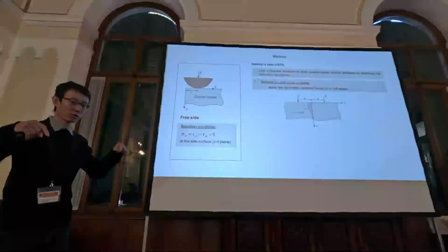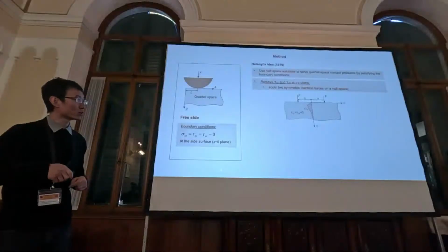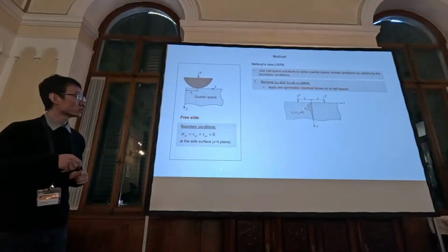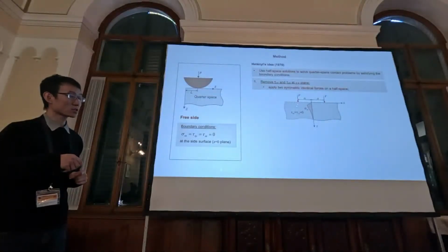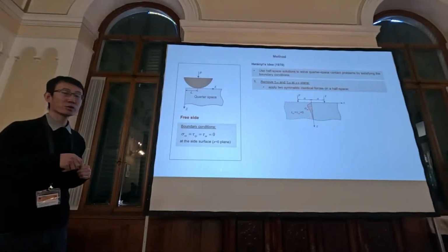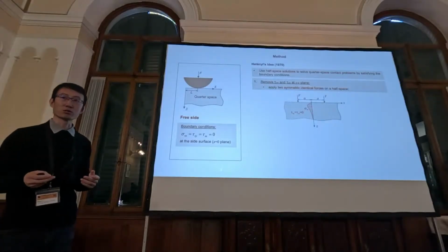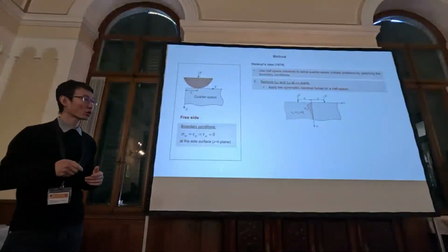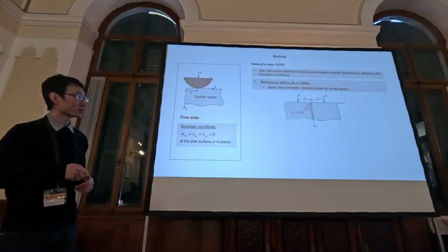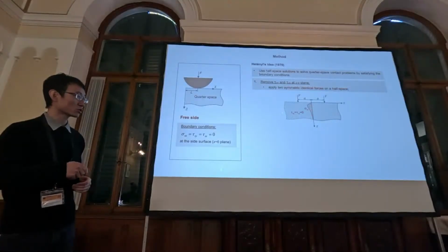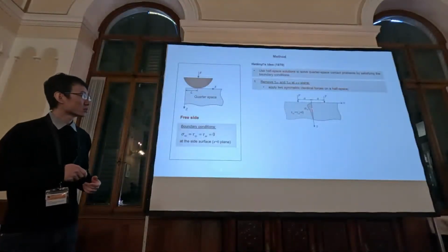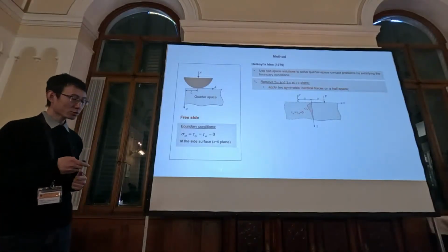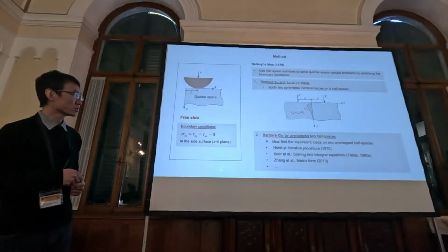This means if we give one load on the top surface of the half space and a mirrored load on the top surface of the half space, then in this middle plane, these two shear stresses are 0 due to the symmetry. Or you can also use the fundamental equations to calculate the shear stresses on this middle plane. So these two shear stresses are 0. But the normal stress still exists. So the second step is to remove this normal stress.